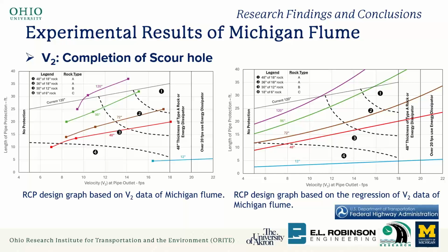In terms of the rock that you use, everyone should realize that it's not meant to be an unlimited longevity installation. Even the HEC says that in every major storm you should go out and check the rock. The rock is meant to be somewhat sacrificial. We want to do our best, but it isn't intended to be a lasting forever solution. It's meant to be a sacrificial solution.